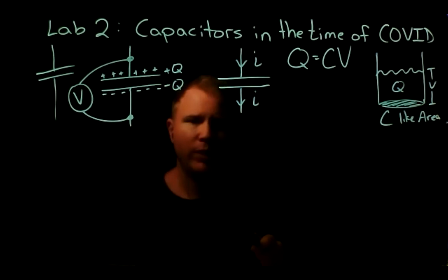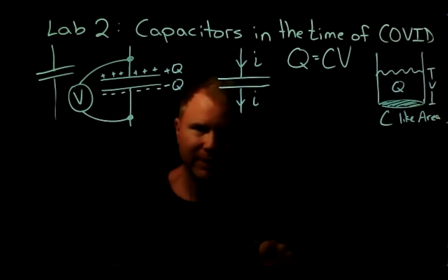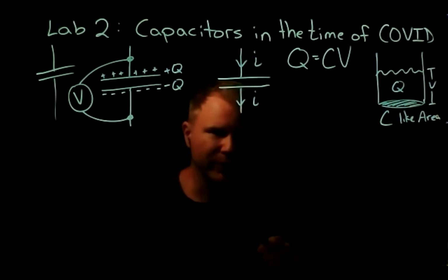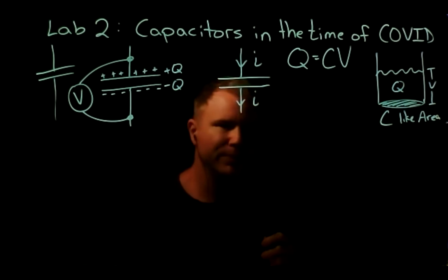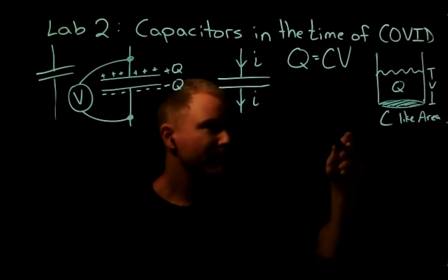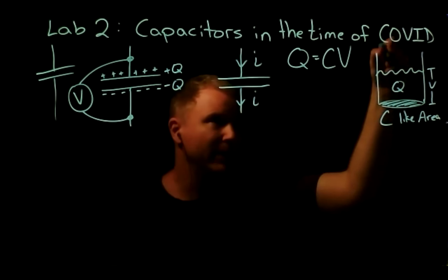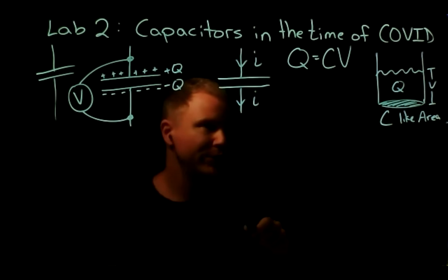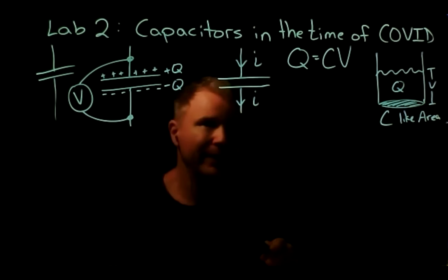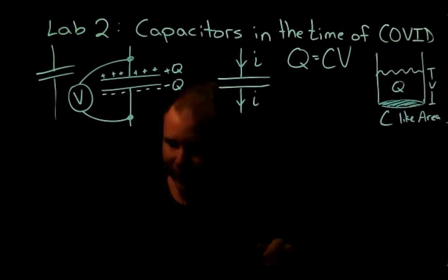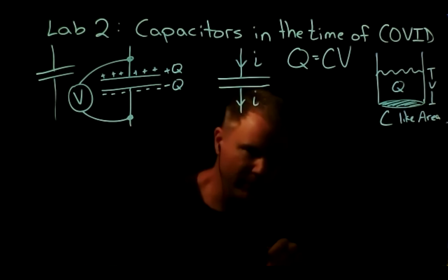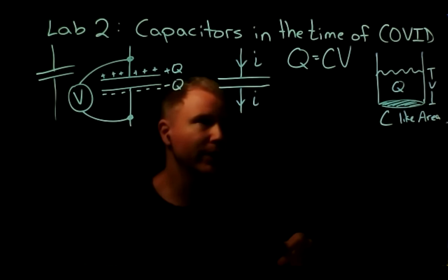So I would say that one thing that's confusing about the name capacitor is it seems to have something to do with capacity, maybe. And so people might think about it as some closed volume and you're filling up some capacity. That's not really the right way to think about it. For an ideal capacitor, this tank can be infinitely tall. You could put more and more and more charge in, and the voltage just goes up and up and up, and everything is fine. Now, in a real capacitor, eventually there'll be a spark across this gap, and so you can't put an infinite amount of voltage on. But that's a problem with the physical implementation of the capacitor, because these plates have to be close together. You can make a spark.